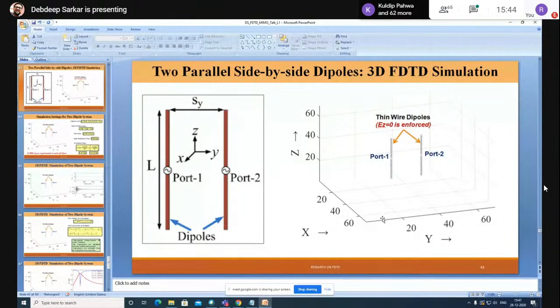That is a fast sweep, and that is extrapolated. The meshing is done at the solution frequency, the center frequency, but we get the S parameters for all the frequencies through extrapolation. But if instead of fast we go for a discrete solution, you have the meshing done for all the frequencies.